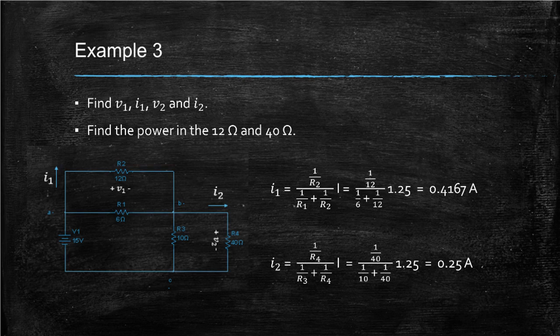The resistors that make up the 8 ohms resistor are the parallel combination of resistor 4 and resistor 3, so the voltages are the same as the voltage of the 8 ohms resistor. Both 10 volts. Now we will use current division to find I1 and I2.